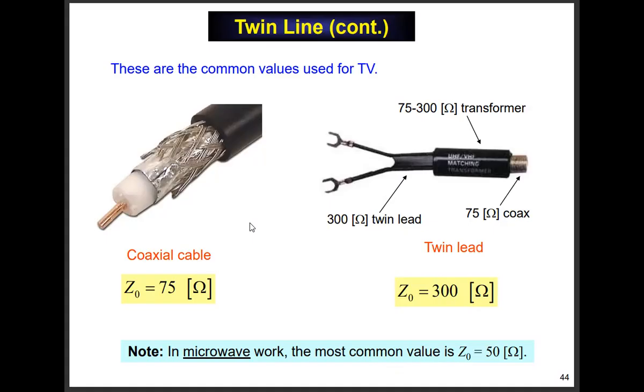Not only that, the reflected signal might even interfere with the system or cause damage if it's strong enough. You don't want reflections. As we'll learn in note 7, if the load resistance is the same as the characteristic impedance of the line, there's not going to be any reflection. And the signal smoothly gets absorbed in the load and no power gets reflected. That's why it's so important. But we'll learn that in note 7.